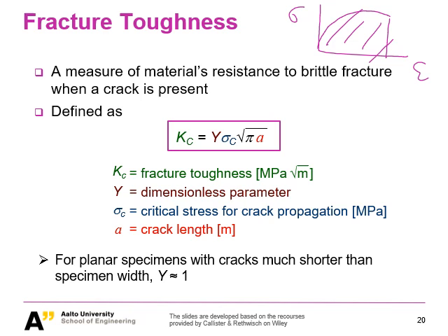I can tell you it's a correction parameter because we want to use the fracture toughness as a material dependent quantity, but when we try to measure it, and for this course I cannot show you all the experiments to measure the fracture toughness, we always need a certain geometry. We cannot go to a really unit crack.